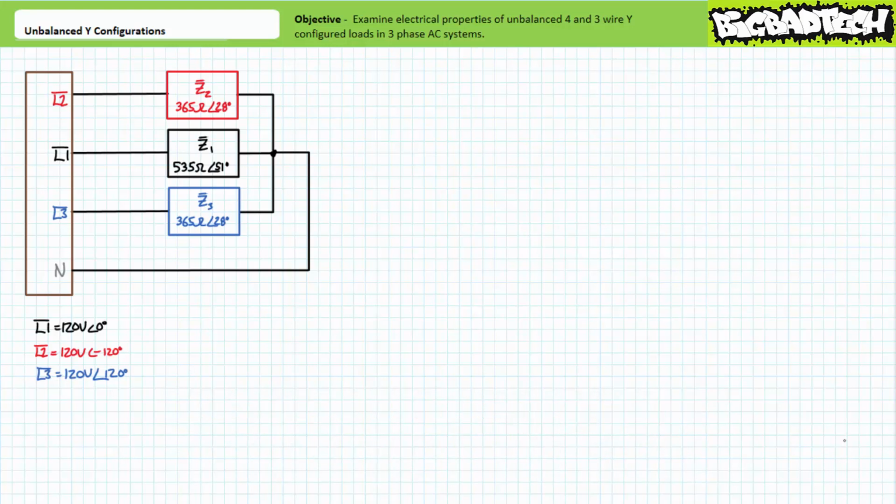Recall that industrial 3-phase AC motors are ordinarily modeled as balanced loads. Given load impedance Z2 and Z3 are identical, this might be some motor that experienced some localized thermal or mechanical stress, or perhaps is just made poorly, such that winding 1's impedance appears altered. This motor might not draw the same current, and as such, neither consume nor exert the same amount of power as it would in the balanced condition. Current through the different load impedance Z1 might be different than that experienced by load impedance Z2 and Z3. Any imbalanced current will travel in the 4th neutral wire. This being said, the 4th neutral wire ensures each branch impedance still directly experiences the line-to-neutral voltages.